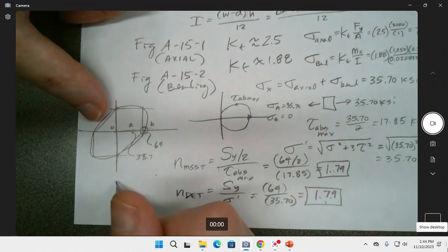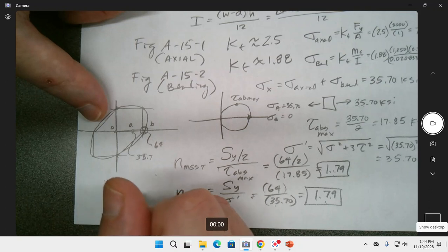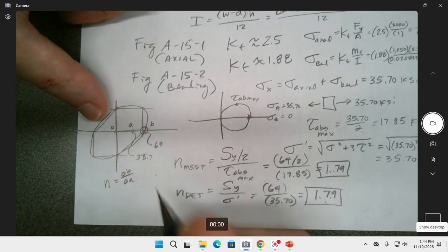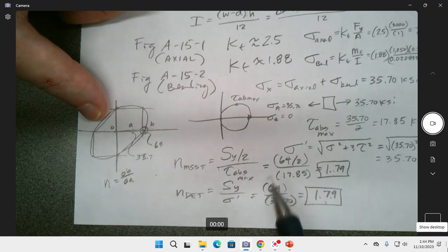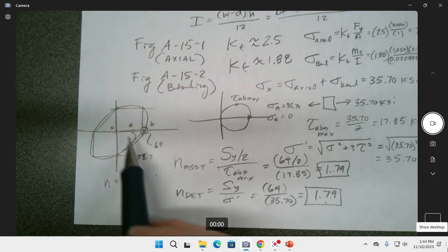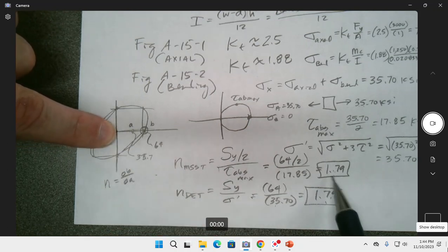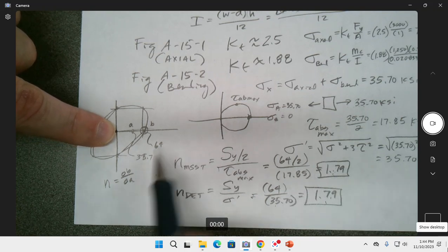So you would just say the safety factor on this would be OB over OA. And you should get the identical thing, except it's just how good your ruler would be. Into this distance divided by that distance. And you should get the same thing as that. And I'm guessing the x-axis would be sigma, and then y would be...